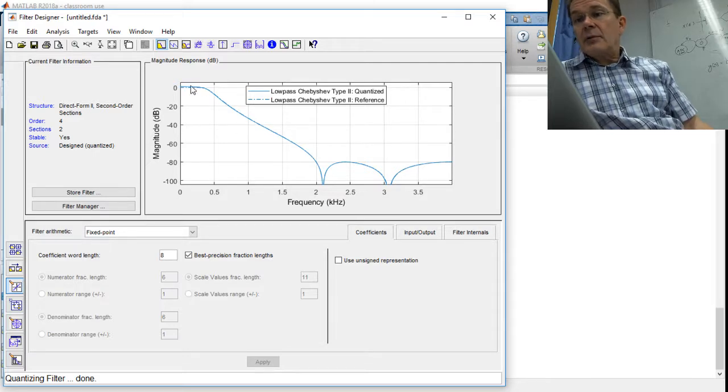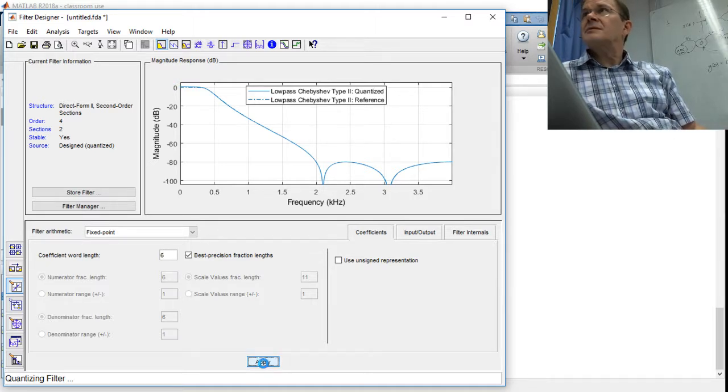All right, now we start getting a little bit of difference here. So even with 8-bit coefficients, we can actually do pretty good calculations. Have you already gone through the FPGA design? On FPGAs, you can do whatever precision you want. The word length is actually up to you to fix. So you can, for example, do 6-bit arithmetic.